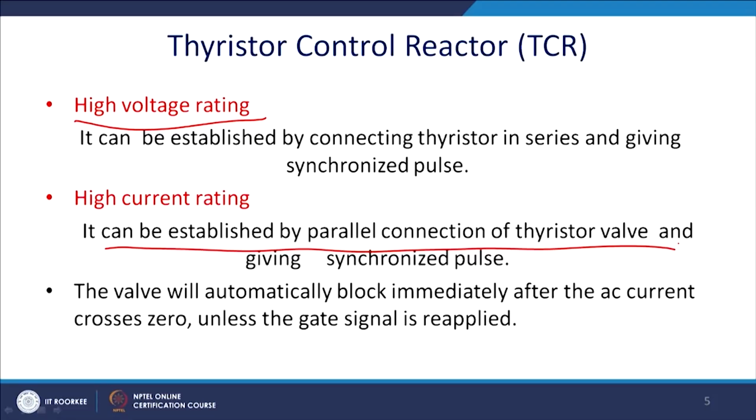The valve will automatically block immediately after zero crossing. So, we will have natural commutation, unless it is reapplied.